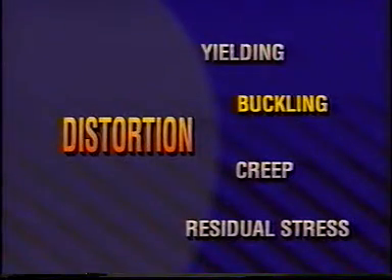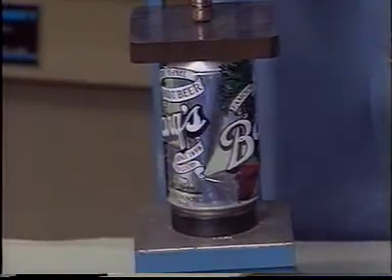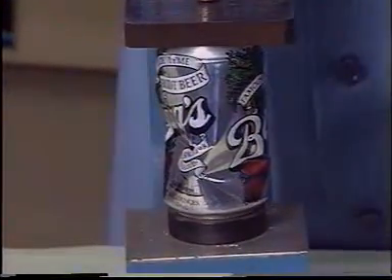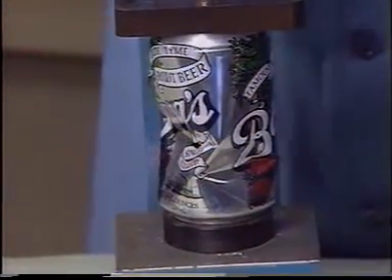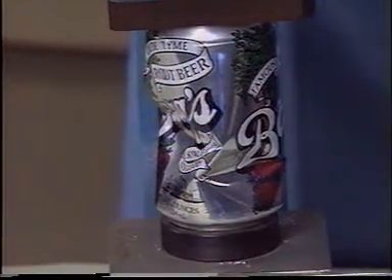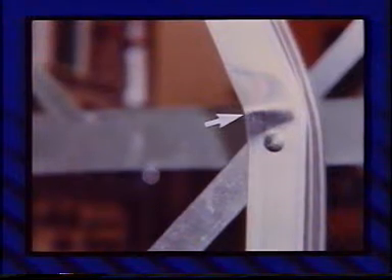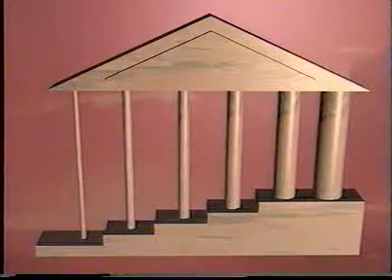Buckling. The distortion caused by buckling is defined as compressive instability. Components subjected to compressive stresses, especially long, slender columns or tubes under axial compressive stress, can distort by buckling, causing entire structures to collapse. Thin-walled tubes buckle or wrinkle on the concave side when bent or subjected to high torsional stress. Since the modulus of elasticity of a metal at any given temperature cannot be changed, its buckling load cannot be changed by increasing the strength or hardness of the metal.